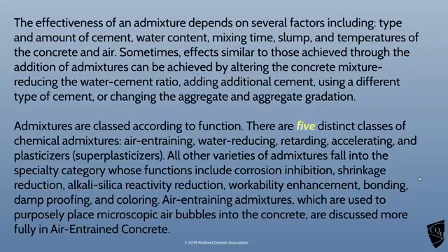How effective is an admixture? Well, several factors hit on that one. What type of cement and how much of the cement you're using, what the water content is, how long you've mixed it for, what your slump test we talk about in a minute is, the temperature that the concrete is being used in. You get different things.